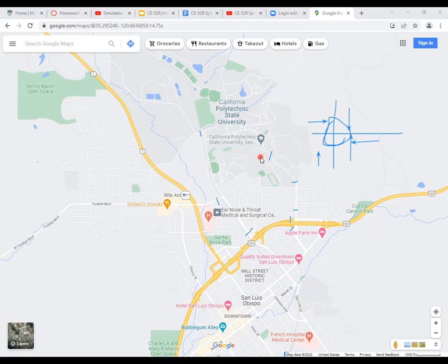Now we have more technology. In the olden days, we used to do license plate surveys, observing the license plates at the starting point and then seeing how many of those plates ended up at different destinations. So we could split the traffic that way too. There are other ways of doing that OD thing, but one more important thing is it's not just about the traffic counts. You have to match the speed profile as well.